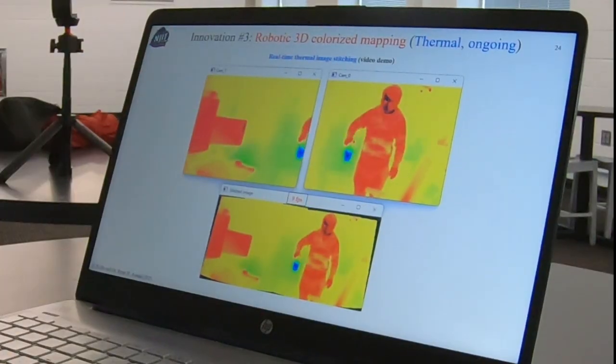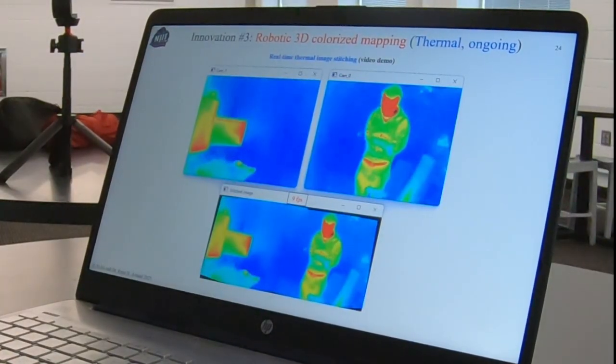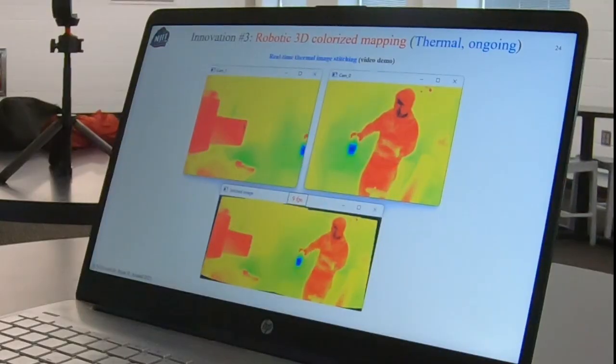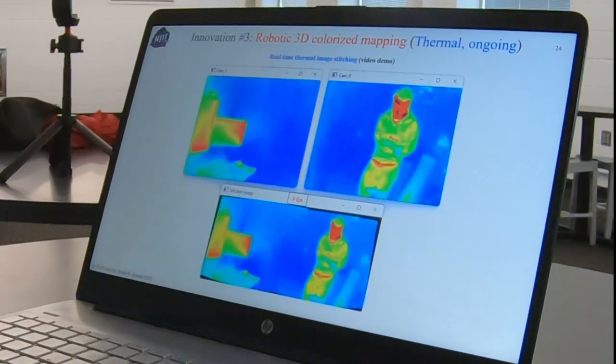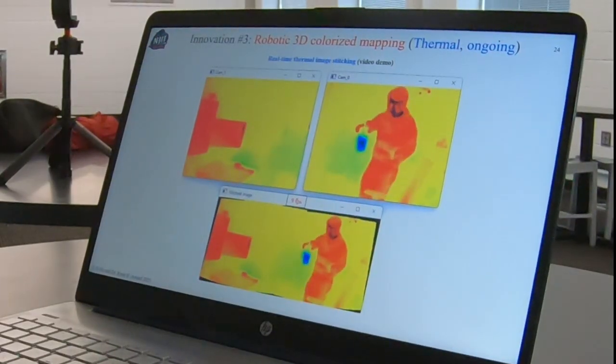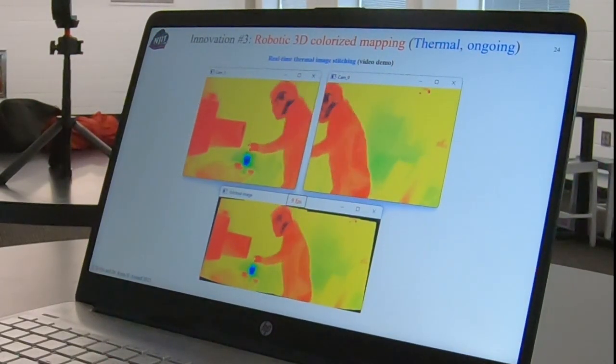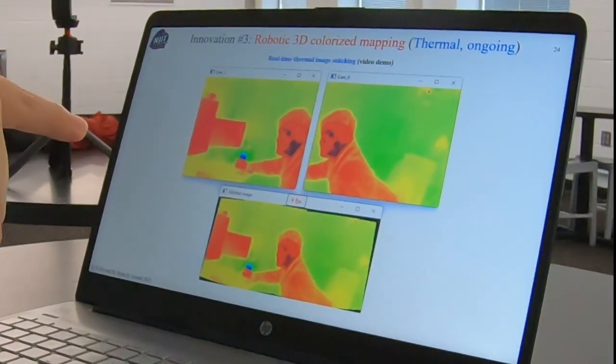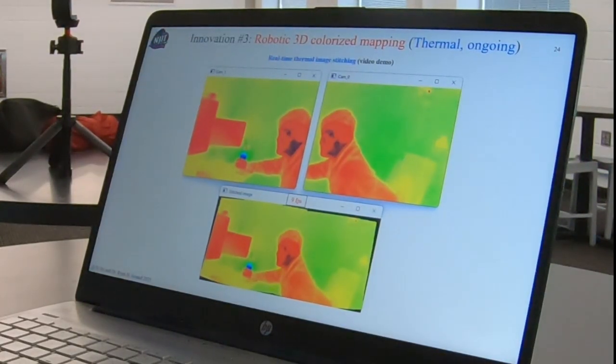So, 2 views. Why do we do this stitching? If we only rely on one camera, to finish a hallway or a room, we have to work around. The 360 LiDAR can get a 360 view, but this thermal camera cannot, so can we expand the field of view? In this case, we can improve the mapping efficiency. We don't have to scan back and forth; maybe you scan over one time, then move to the next place. That's the uniqueness of this system.